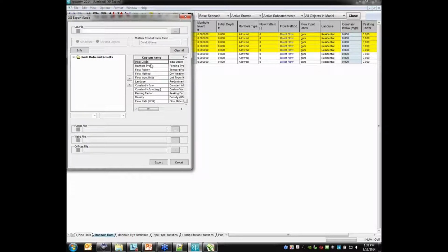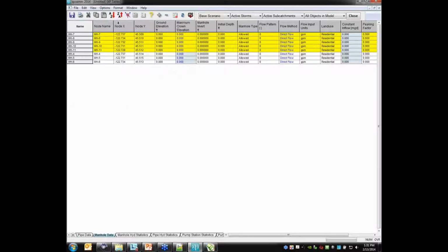I'm sure you've seen the limits. This is something that is independent of XPSWMM, but it's the spec on the shapefile field name. So you probably had to go through before and type depth and type and pattern. And then if you hit export and you come back, you have to redo that. A nice alternate way to do that, especially if, like a lot of us, you have a table and you really like the way it looks, is to copy that table and then prepend or append GIS to it and put the headings in here as you want them. So you could format that to be what you want it to be called, and then it is persistent. So every time you had it and you selected and filtered the way you want, you could just dump it to a shapefile.